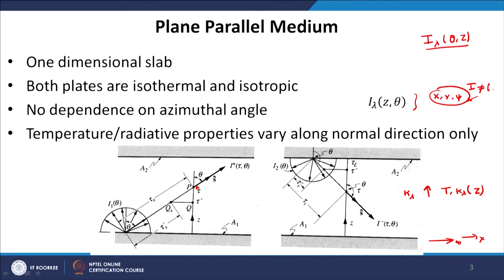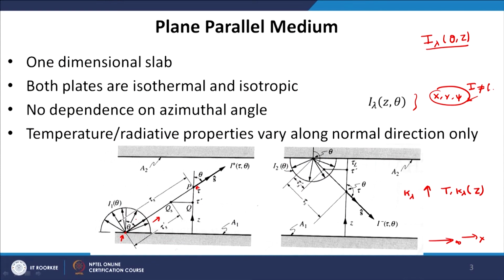Okay. In the first part, the intensity originates from the point on the surface 1, towards point P. From here to here it undergoes emission from the medium, it also has contribution from radiation emitted by the surface. So, it undergoes all the four processes: attenuation by absorption and scattering, and augmentation by inscattering and emission. Now, we use the coordinate system.